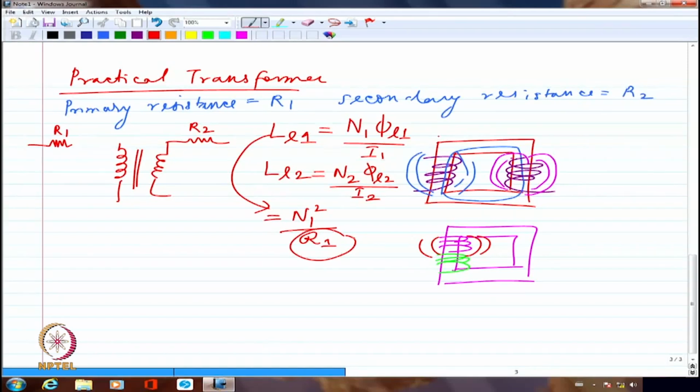If we consider the reluctance in the iron core, the permeability keeps on changing depending upon at what portion of the magnetization characteristics we are operating the machine, right? So the permeability is not a constant in the case of a ferromagnetic core. So the inductance will not be a constant, depending upon the magnetization characteristics portion where we are operating.